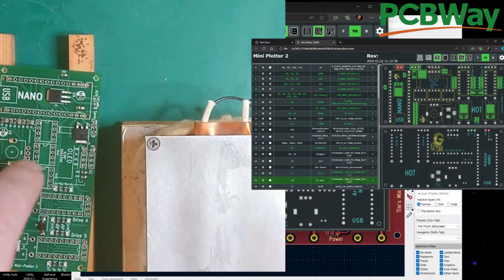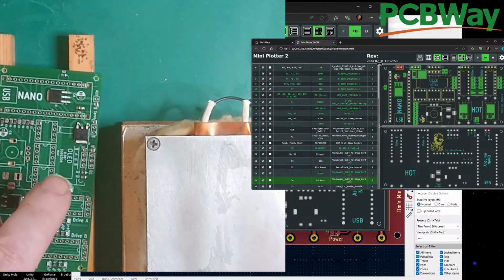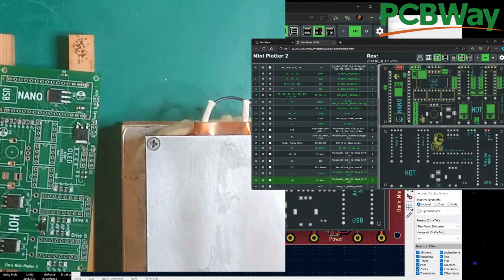Because obviously this on a piece of wood is going to cool down a lot faster than this plate is going to cool down. This is why, well, I'm just repeating myself. You should always start at a temperature lower than what you need, and then work up once it's reached that temperature, because you will get it overshooting, because it can't cool down as fast.